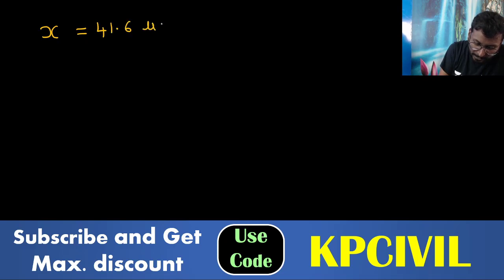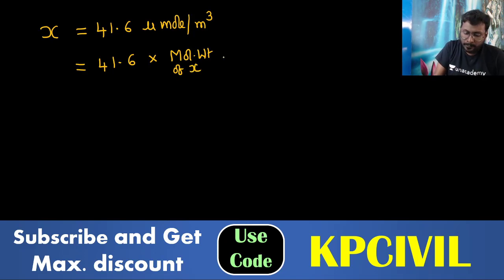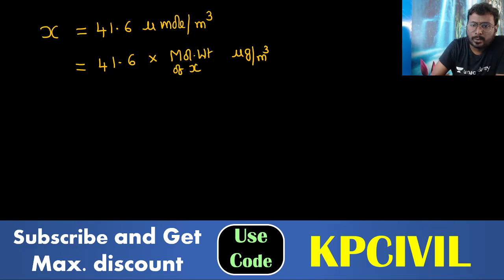41.6 micromole per meter cube. Now I am converting to microgram. X converted to microgram. How? Multiply with molecular weight. X is equal to 41.6 into molecular weight of X, in microgram per meter cube. When you multiply with molecular weight, micromole is converted into microgram. So 41.6 into molecular weight of X.